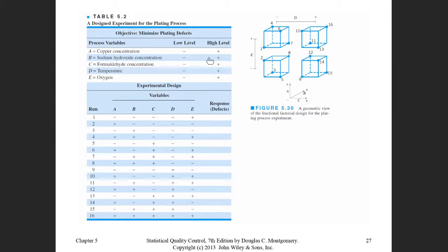One example of SPC that is very famous, and that we have as a separate course, is the design of experiment to optimize a process. For example, here to minimize the plating defects. To optimize the plating, you can use the process variables, like here we have for the plating, and then you apply design of experiment to optimize the production or even the service.